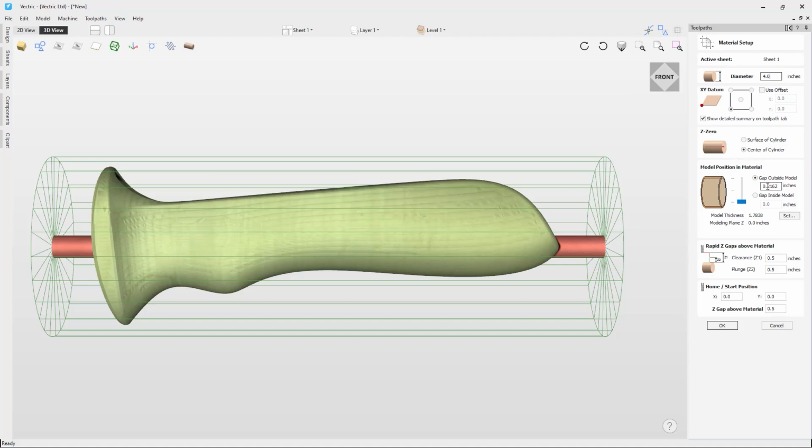Now the reason for that is to give me room for error, because if I'm cutting this out and I'm not sure that the material has any ridges or any uneven parts, what I don't want is the model to meet the edges and then to reflect that with the cut having those uneven edges. So by having the model inside the material and leaving a little bit of a gap between the inside and the outside edge of the actual material itself, it can machine that edge away and then only leave our model as it's looking now, so we get a nice and clean finish.